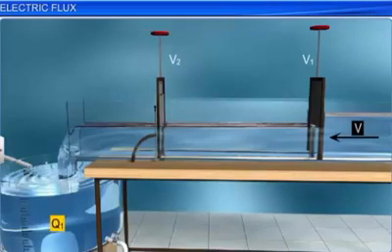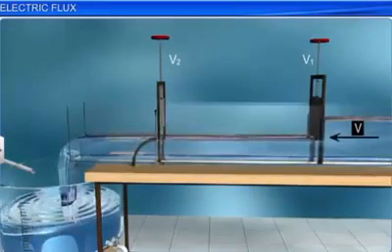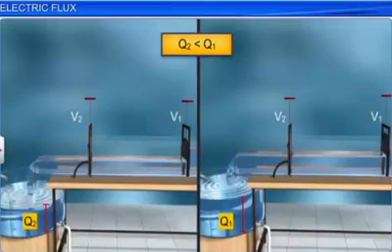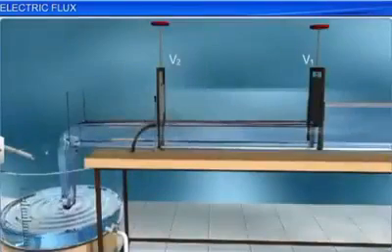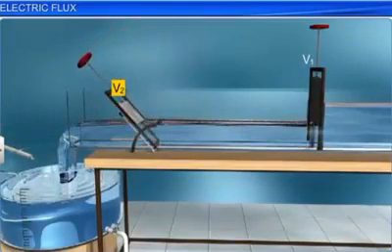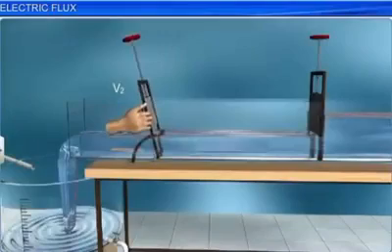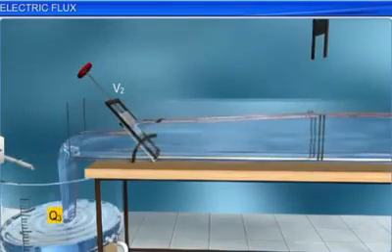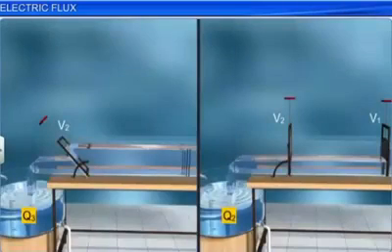Now, lower the closing plate of V1 without changing the position of the plate in V2. Measure discharge Q2 again for 5 minutes. Q2 will be less than Q1 as the area of opening in V1 has decreased due to the lowering of the plate. Then, swing V2 until the bottom line of the plate just touches the top surface of the water in the downstream. Remove valve V1. Measure discharge Q3 again for 5 minutes. You will find that Q3 is equal to Q2.